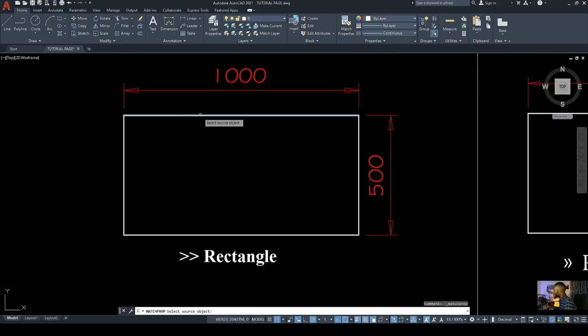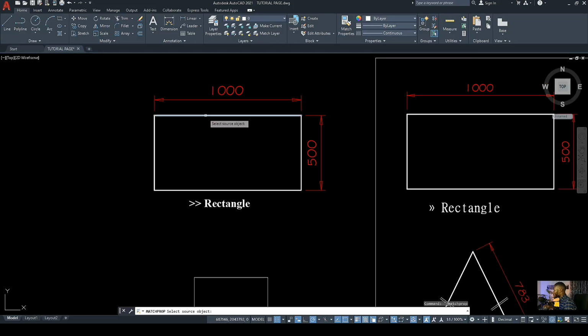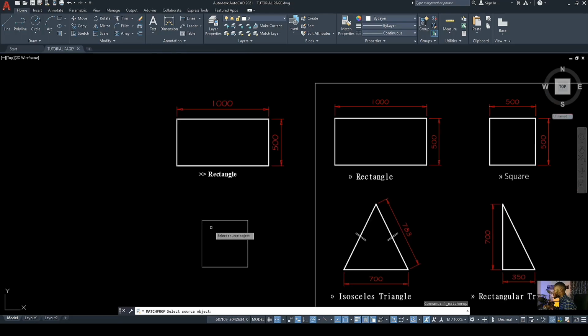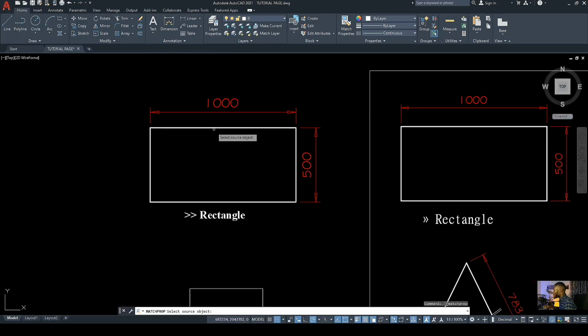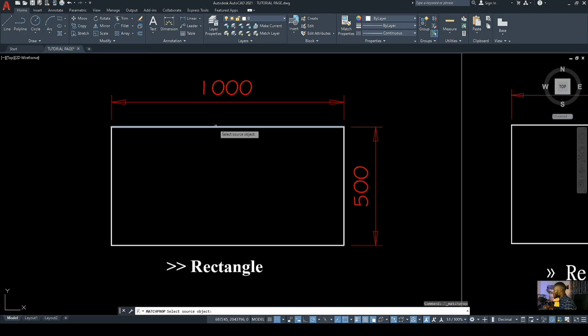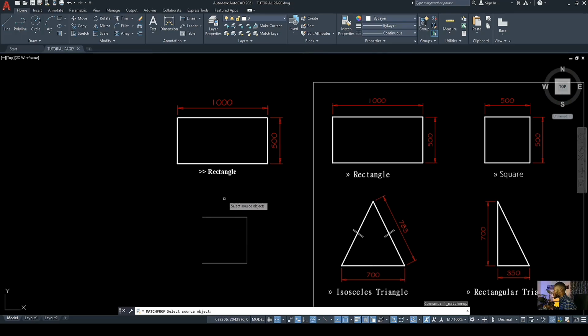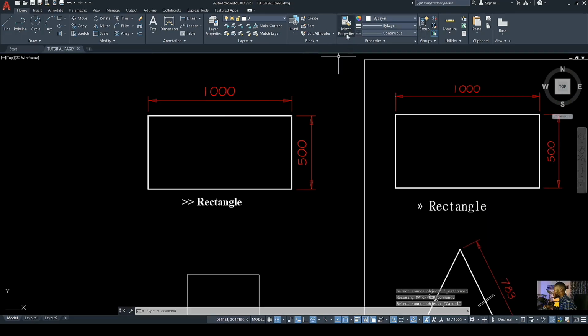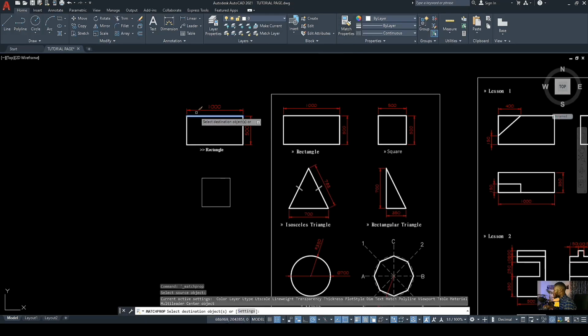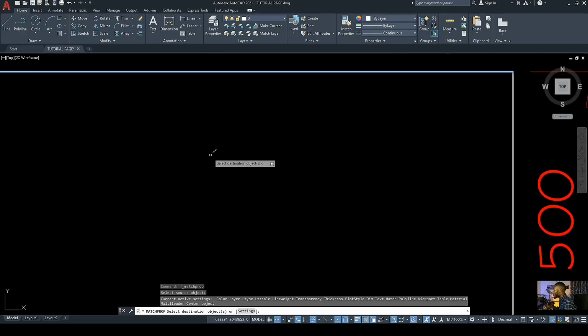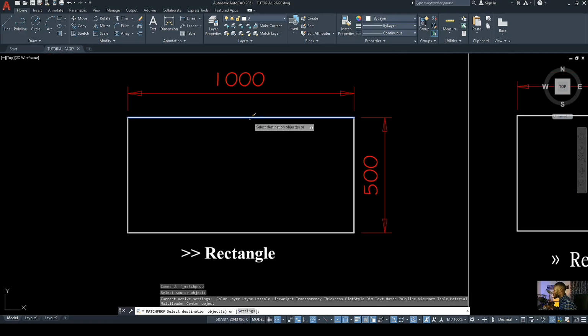Like I said, it helps in transferring the property of an existing element or shape to a newer element. So now we can transfer the property of this line to this one, so that we have identical properties. Having clicked Match Property, we select this, click on this line, and we've copied the property. You see a paintbrush pops up immediately we click on the line.